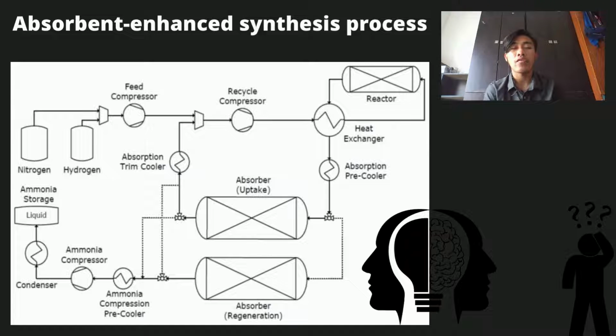one bed volume of stoichiometric nitrogen and hydrogen is fed to the bed to displace the ammonia gases. The emptied bed is repressurized to the reaction absorption pressure with a stoichiometric mixture of nitrogen and hydrogen, and then we connect it to the reaction absorption loop. That's all from me.